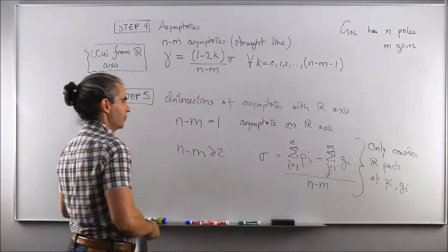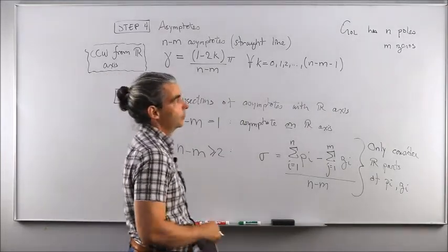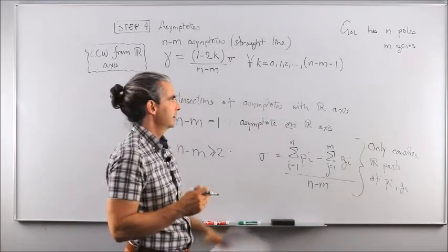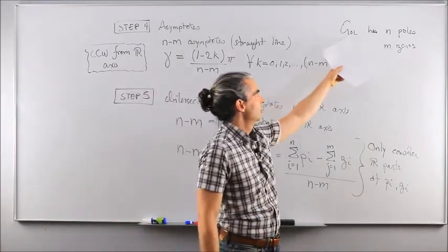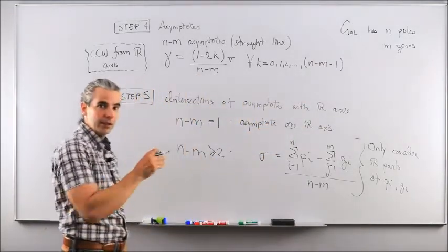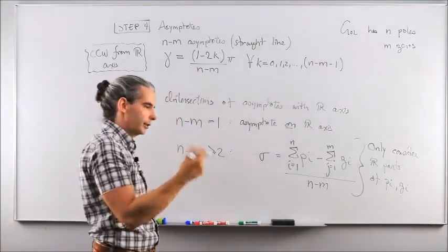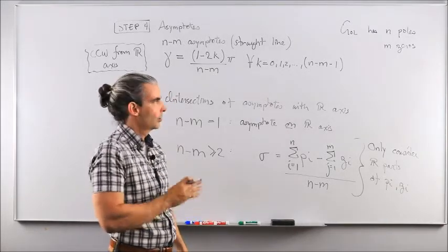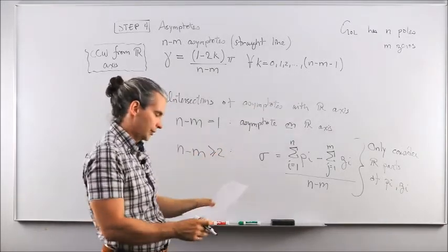Poles and zeros of what? Of the open loop transfer function. So unless otherwise noted, everything is done from the open loop transfer function's perspective. There is only one step in the entire procedure for which you'll need to calculate the closed loop transfer function and use it. But otherwise, everything is done with the open loop transfer function.